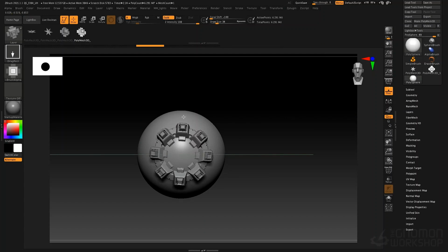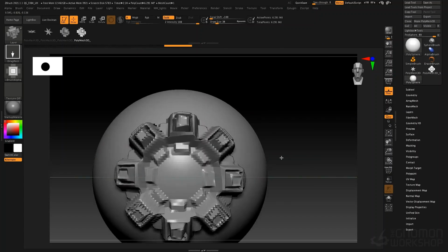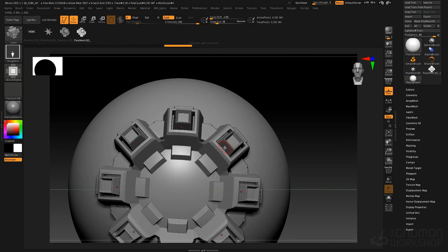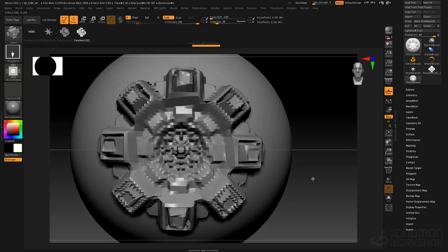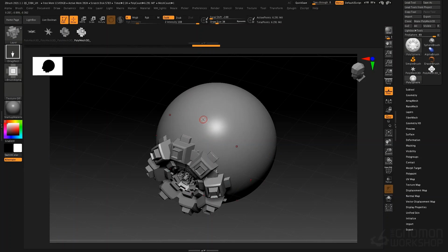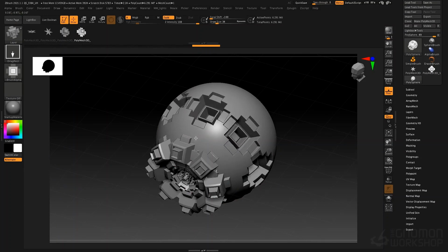Click and drag. You can draw these alphas out, and they will blend together as they meet. There we go. And then we get a shape like this. Let's bring it in here, hold down the Alt key, click and drag. It's almost like a mandala effect here. So it's quite cool. We can come over here, hold down the Alt key, and subtract these alphas here.